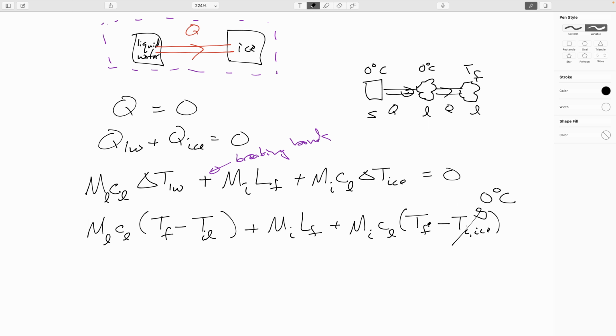The temperature difference will be Celsius degrees, and a Celsius degree is a Kelvin. So I don't have to convert my temperatures to kelvins if they're differences. I can just leave it in Celsius and it's okay. So here I'm leaving it as a difference so that I can go ahead and stick in a 0 right away in order to make the numbers easier to compute.